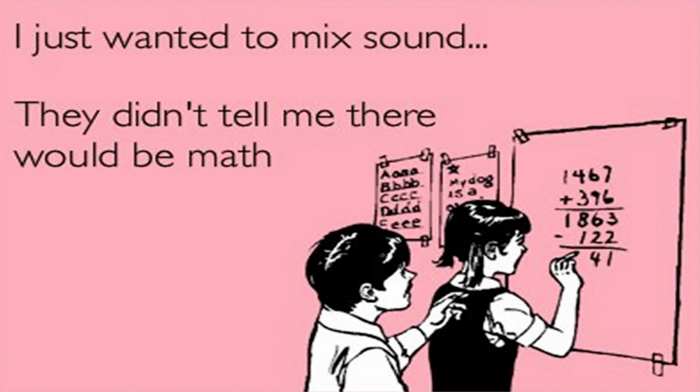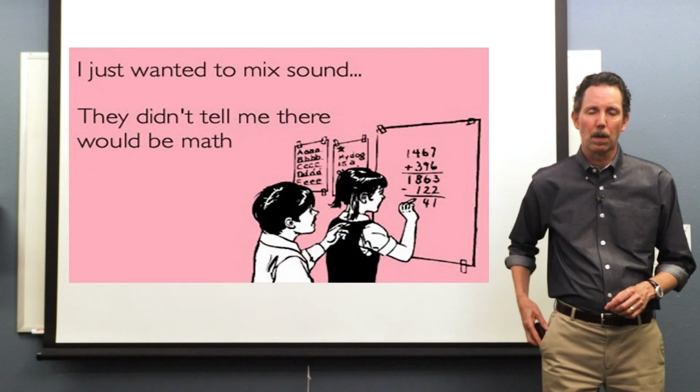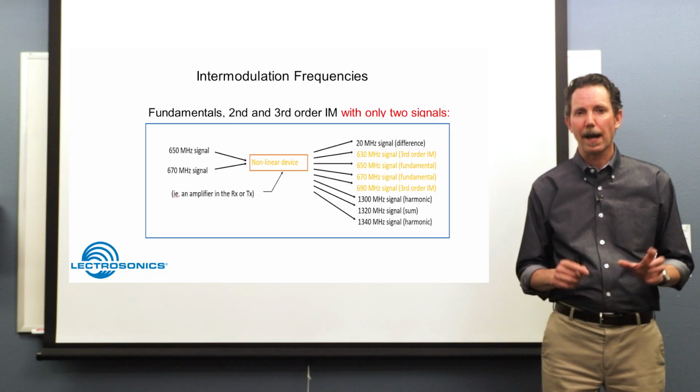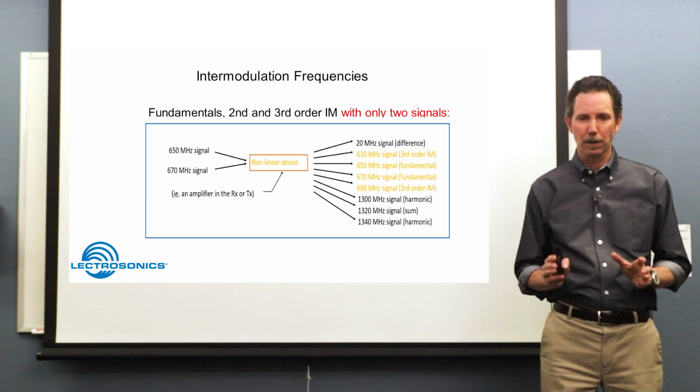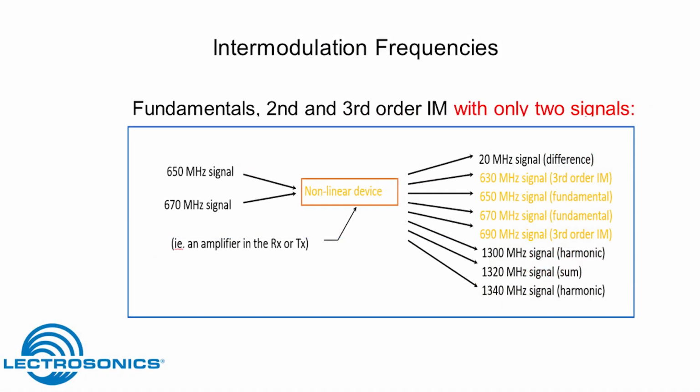All right, so what is the concept behind frequency coordination? Well, all wireless microphones have the issue of what's called intermodulation. What does this mean? Essentially, if you've got two different RF signals generated in your transmitters, and those signals get picked up in other devices, like the other transmitter next to it, or a receiver, or an RF amplifier, anything with active RF circuitry in it, there can be phantom frequencies generated mathematically inside these units. It doesn't happen in the air, it happens in active RF devices, like transmitters, receivers, RF amps.